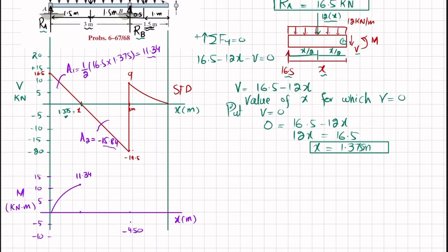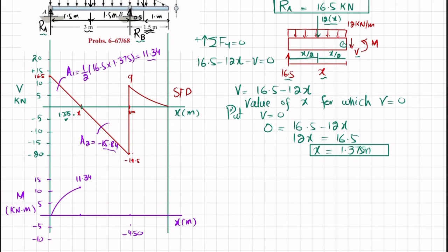4.50 minus, and again you can see that shear force is a horizontal line of degree 1. So the bending moment will be a second degree curve and the slope is decreasing, so it will again be clockwise. So we will join these two points again like a curve. So it will be like this.